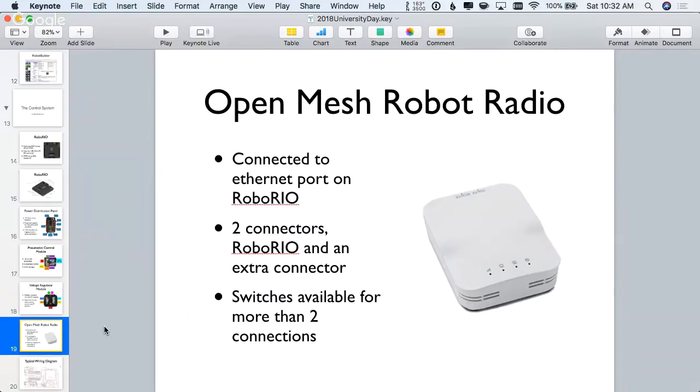The little connector is not made to be put on a robot. Especially last year, the year before, when robots are driving over those defenses and bouncing around like crazy, those connectors kept popping out. Or they just pop up for a second, then they pop back in again. And then the radio would stop working. So if you watch those matches, there were more robots failing in the middle of the match than any other year because they were bouncing around so much.